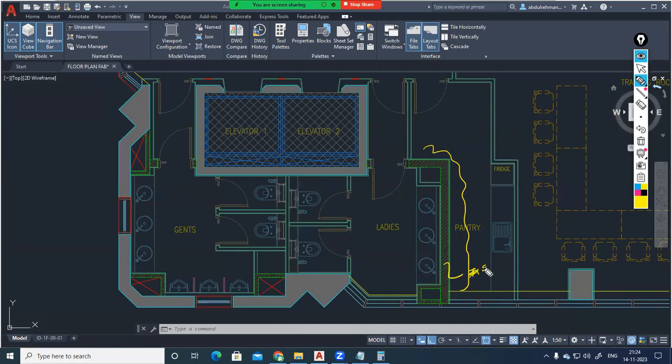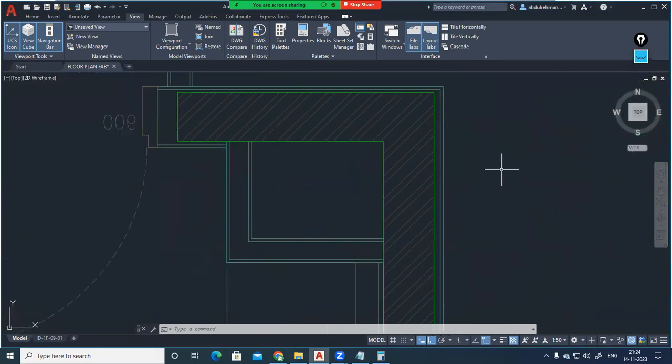This is like, okay, wall 1, or this will be wall 2, this will be wall 3, this will be window 1. They'll be marking in the drawing that what is this window 1, what is this wall 2, like that. Separated drawings they will provide. In that drawing, in-depth details of material they will provide. Who will provide? Architect. Normally in the architectural interior design drawing, ID layout, we will be having the material details. But generally, normally, this double hatched lines will be representing which one? Brick wall only. Brick wall.